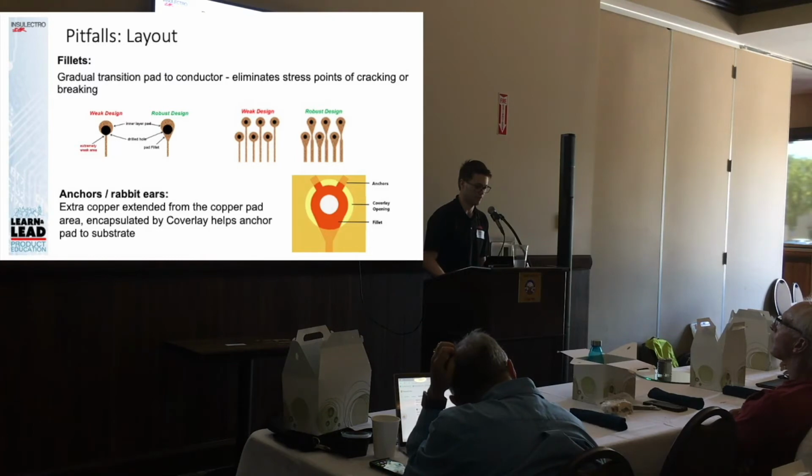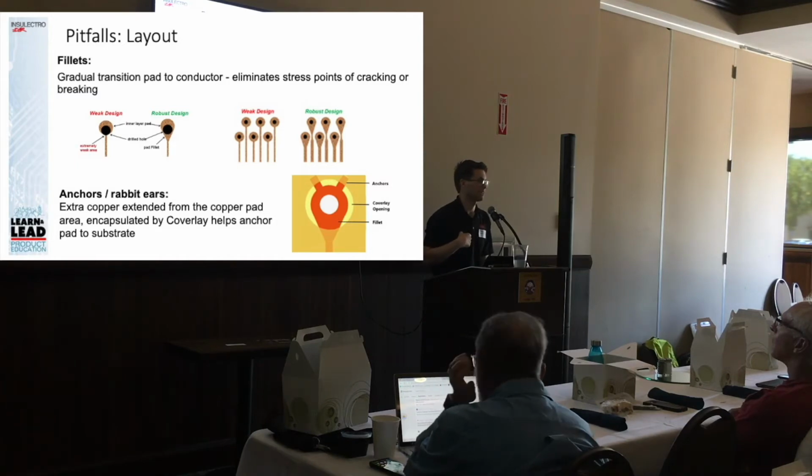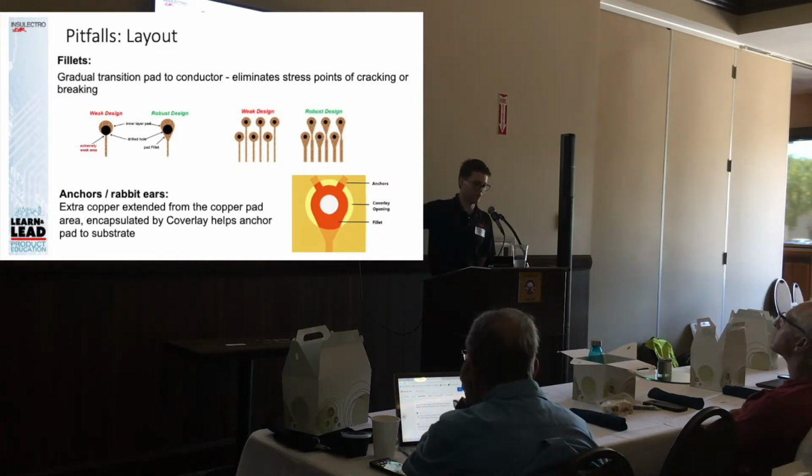If we do not fillet those edges, we get stress concentration factors at those edges, and that can cause crack initiation. The other half of it is, from a fabricator standpoint, we want a little bit of tolerance, so in case our drill moves during the drill file, we're not puncturing that connection and again creating an unreliable connection. On the left-hand side, if we have a connector of some kind, we can lay those out differently, but again, the fillet is very important to increase the reliability of the product.